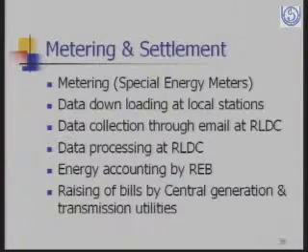And the data downloading at local stations, data processing at RLDC, energy accounting, how much of losses are to be charged to the utility, which utility along the way has how many losses, all this, and raising of bills by central generation and transmission utilities also is done through the RLDC offline. Offline means you can do the accounting later.